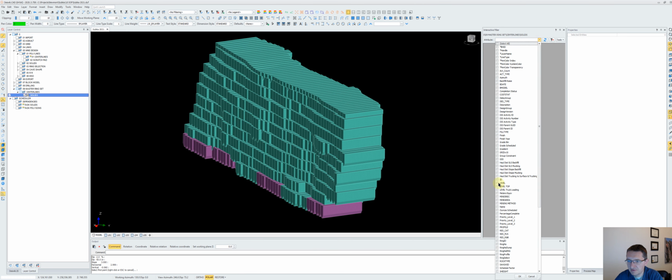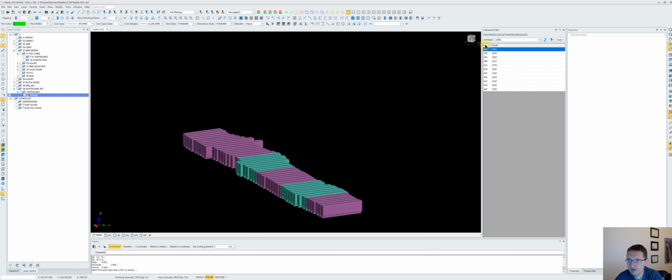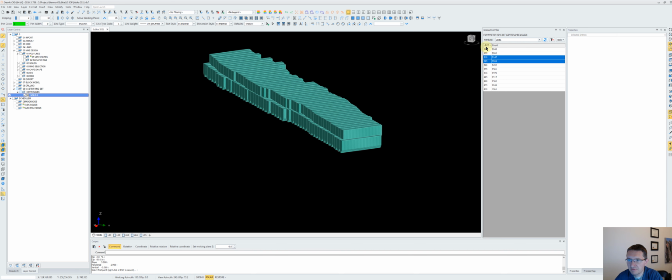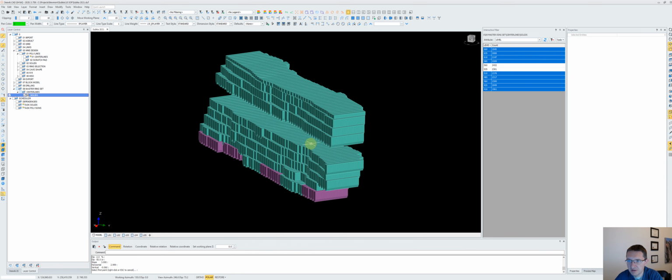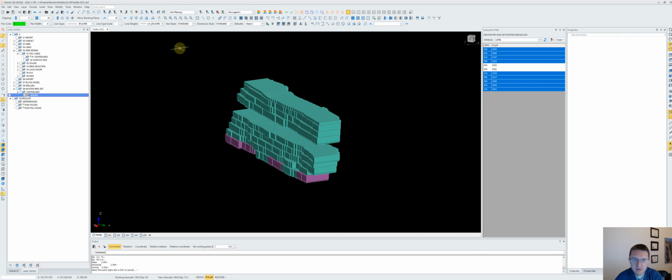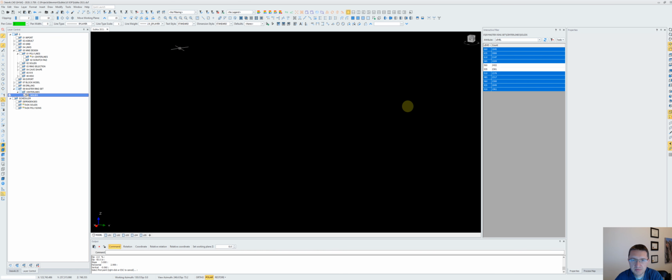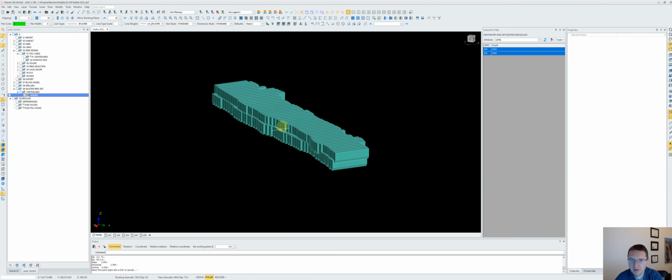And then I'm going to find level. And we're just going to take a level out of the middle. Maybe these 2 levels are the 2 we'll keep, 560, 535. All the other levels we're just going to delete. Okay, it'll speed things up. So there we go. It's a lot smaller now.